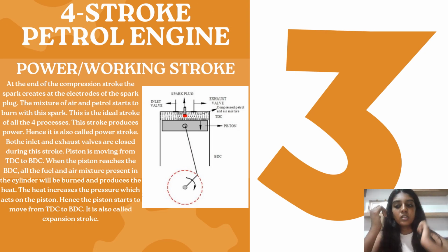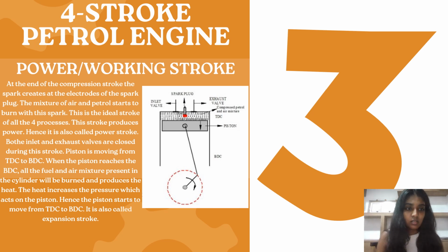Next, we have the power or working stroke. At the end of the compression stroke, the spark plug creates the spark. The mixture of the air and petrol starts to burn with the spark. This is the ideal stroke of all the four processes. This stroke produces power and hence it is also known as the power stroke. Both the inlet and exhaust valves are closed during this stroke.